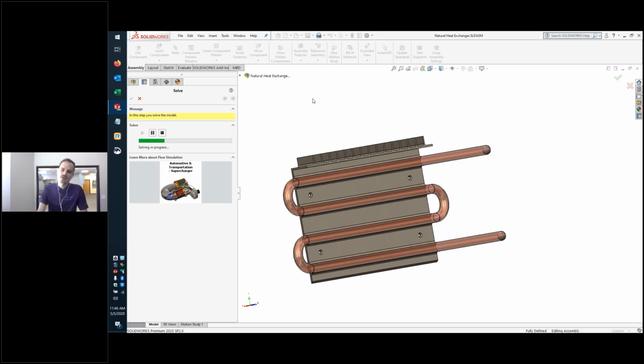By the way, while we're talking about it here, both the SimXpress tool and what we're looking at here with FloXpress are using the same basic solver as the full version of these products. And if you're not aware, the solvers do utilize multiple CPU cores. So of course, if you have a modern processor with, let's say it's an Intel Core i7 with 6 physical cores, they'll take advantage of all of those, and in addition to the clock speed. So that's one of the most effective ways you can speed up a simulation like this. Of course, RAM is important as well. Sylvia, I'm not sure how much RAM you've got. I'm at 16 gigs right now, which I guess is good enough for me to not complain. And that'll control how large of a simulation you can run.